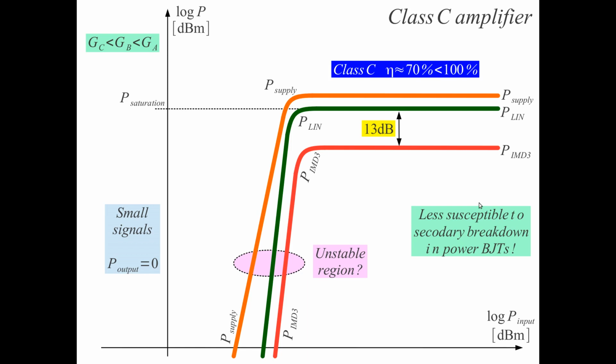So it's important to know that a transistor designed for Class C amplification may actually break down in a Class A amplifier because of a different transistor design, different selection of the power equalizing ballast emitter resistors in the bipolar transistors. MOSFETs do not have this problem. MOSFETs can easily work in Class A with any kind of modulation.